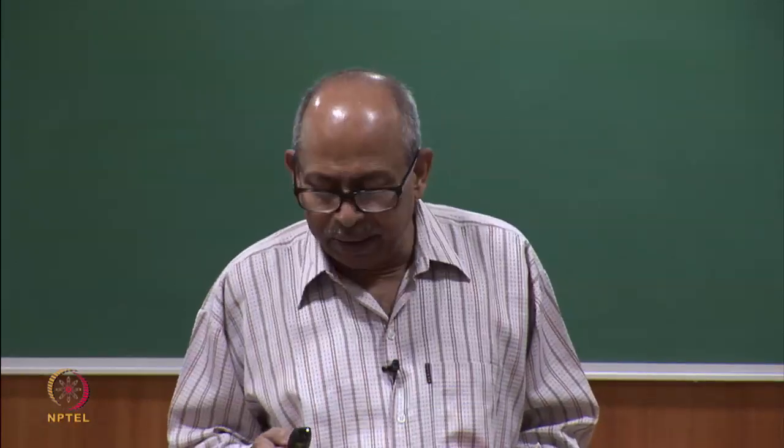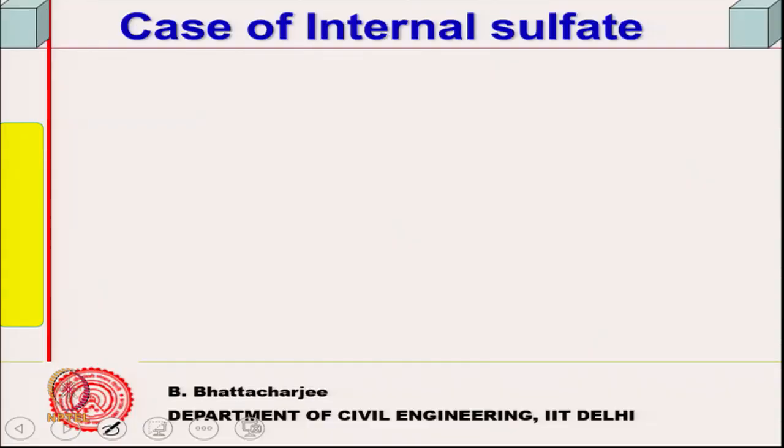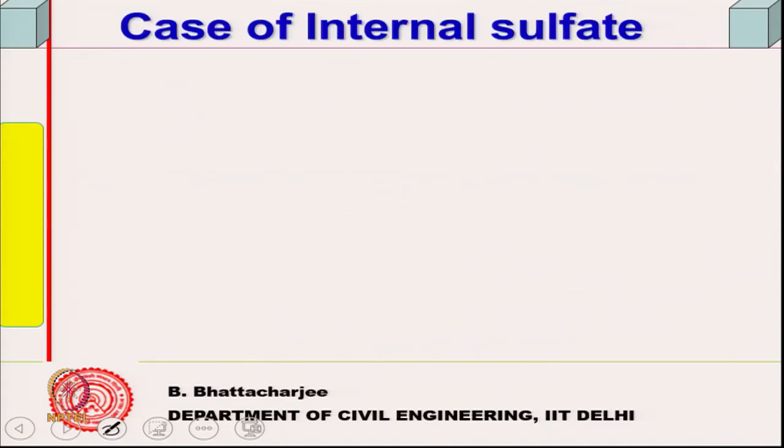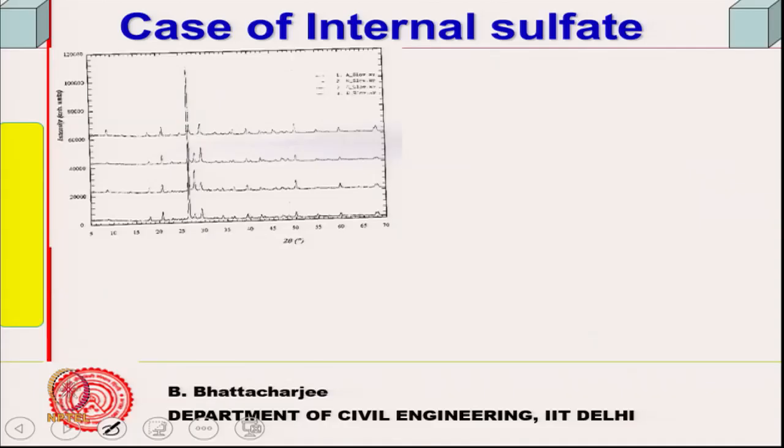So, to verify this, of course, we did an instrumental test, X-ray diffraction of the product. Now, when you do X-ray diffraction of the product, it was at around 9 degrees and 18 degrees, you see. Normally, this is for normal hardened concrete, XRD of a concrete specimen, right, generally produced from ordinary cement and good water. So, this is the X-ray diffraction pattern of normal concrete. We do not find ettringite peaks there after 7-8 months old concrete, but when we looked into this concrete, there are always ettringite peaks.